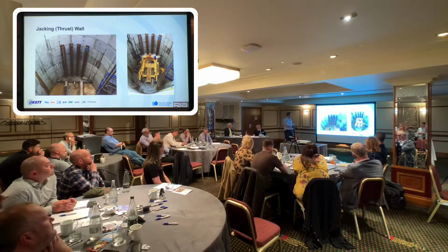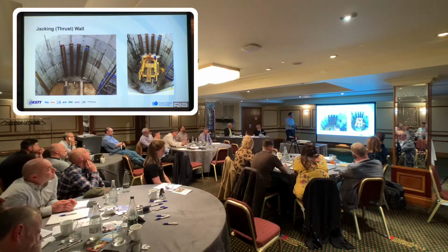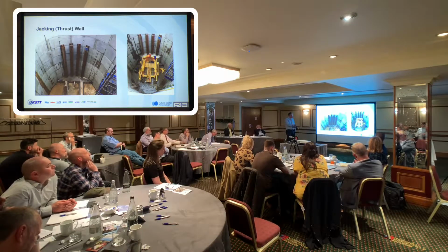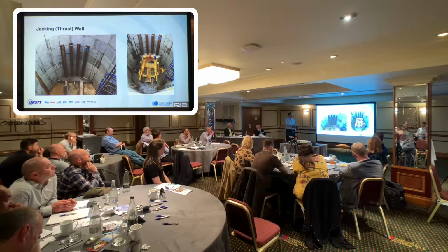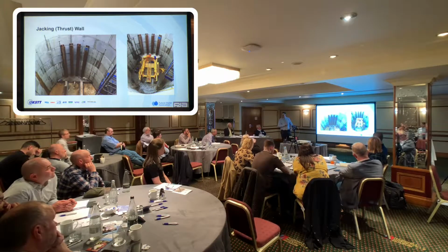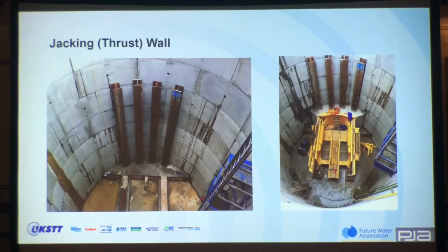You can see this is the shaft, and these are the columns when it's just been put in before the machine comes in. Then the rig gets put in, shutter off the sides, and you cast those in concrete. So the action of that, when it's loading up and pushing the pipe this way, is that you can take benefit up through the rings, help to distribute it, and then after that, the back wall can be broken out, and the steels can either be burned away or sacrificed, or most contractors, I'm sure, will want to get them back wherever they can.